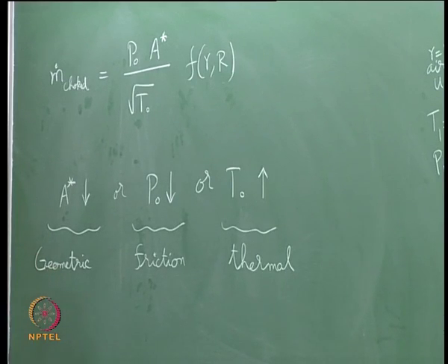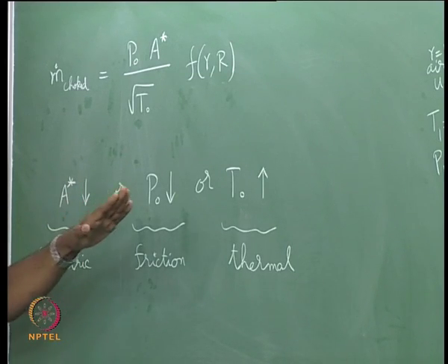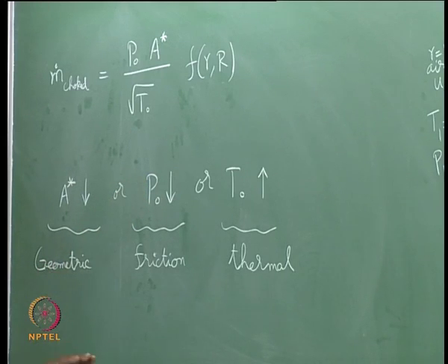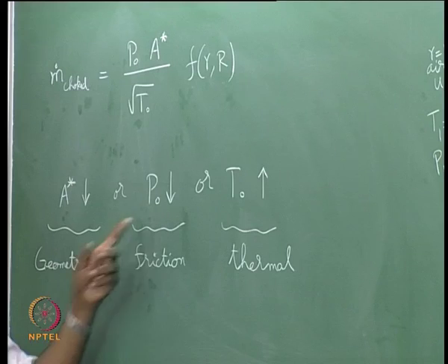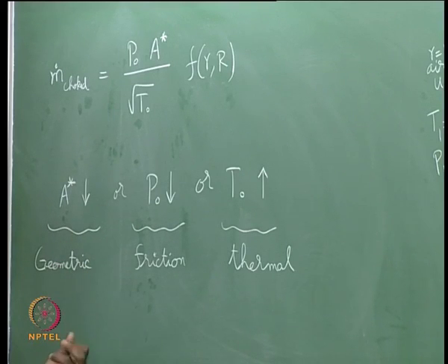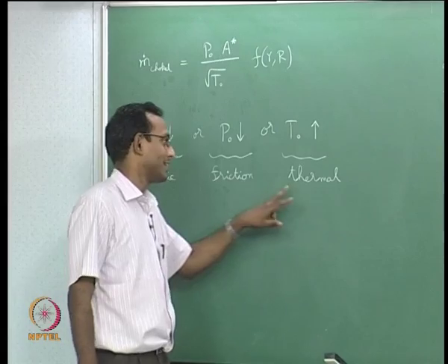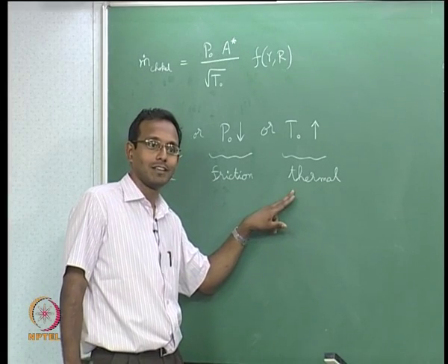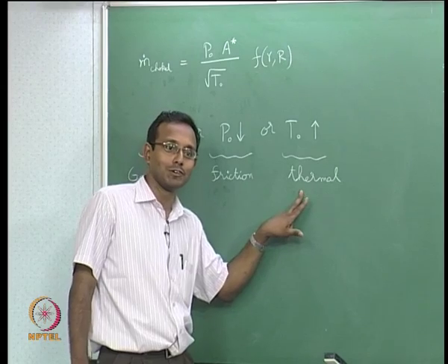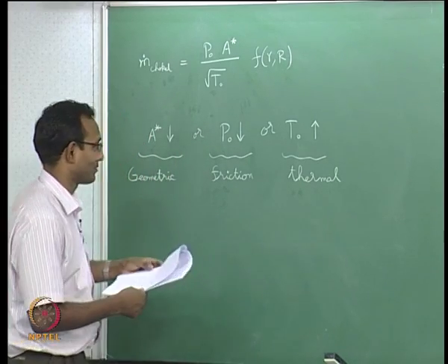You want to think about, if I have protrusion in my duct, if this is the duct, I don't want a protrusion straight in, but I may want to have a protrusion that's slant. That will have lesser P naught loss, that will help a little bit. Those are all things which will take you to choking condition anyway because of P naught loss, but it will be lesser P naught loss, it will postpone the choking point. Or I can think about cooling, very useful thing to do. If you want to avoid choking, cooling is a very nice thing to do.